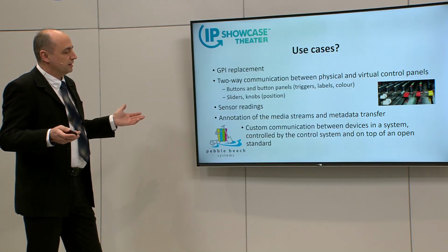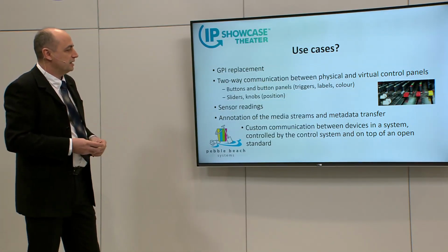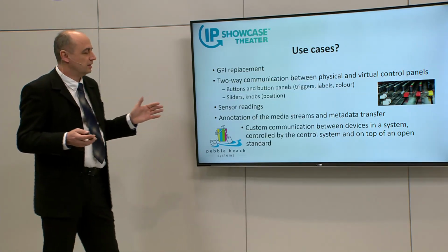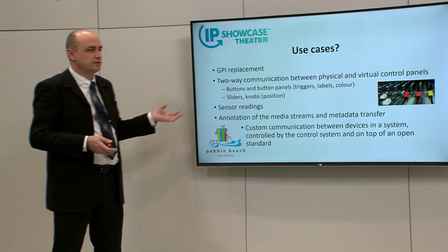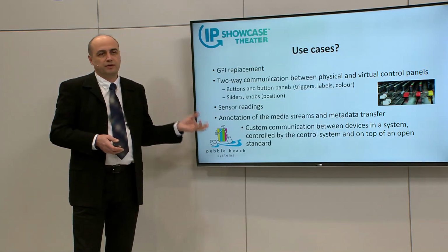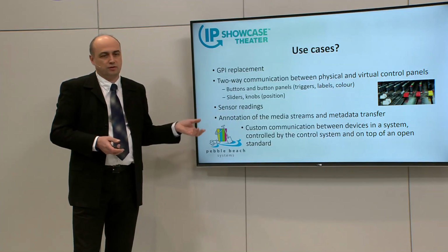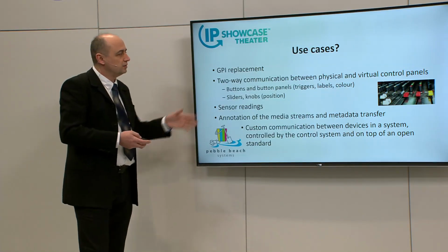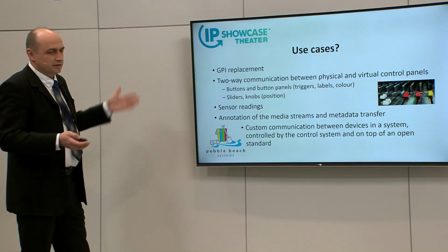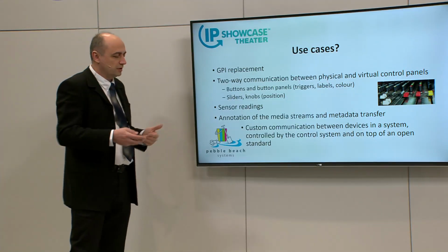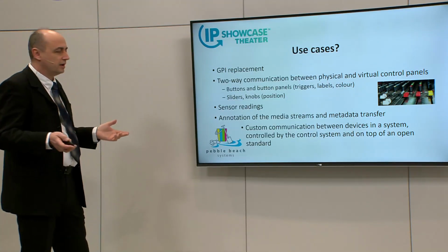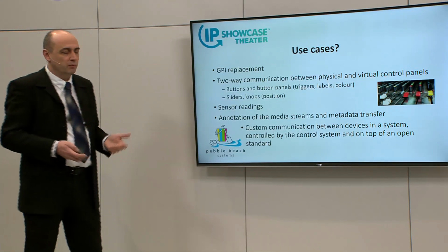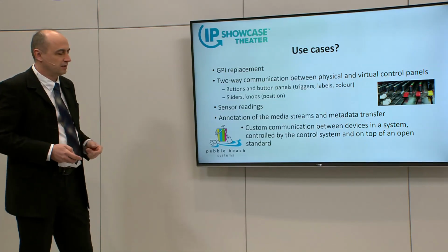But also another excellent thing about this is that it also allows custom communications between devices to be implemented on top of that. As you have seen in the message format, we have the payload field, which is basically a JSON structure. So you can put any even proprietary data in that and still use all the other benefits: IS-05 connection management, grouping, and all that, and you have a standard protocol to transfer your data, even if you are working on a project where you have to connect to specific devices.